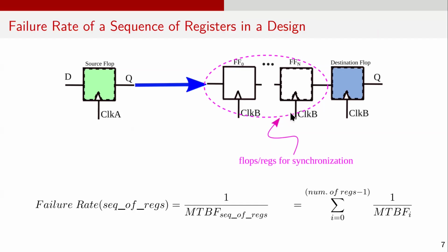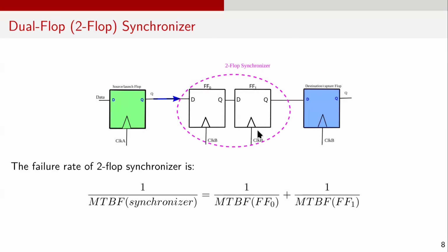the most widely used circuit structure to transfer a single-bit signal across clock domains and tackle metastability is the two-flop synchronizer. In fact, most ASIC standard cell libraries provide this as a fundamental building block. This is how it works. If the first flip-flop goes into a metastable state, the second flip-flop provides extra time for the signal to resolve.